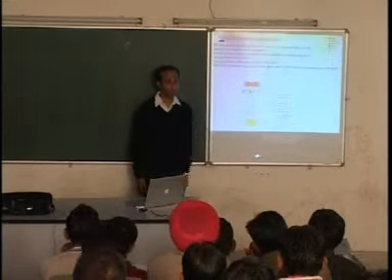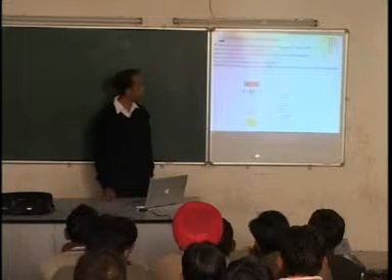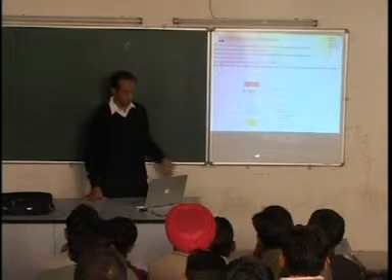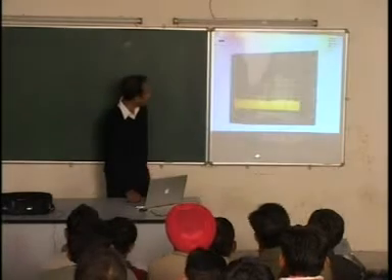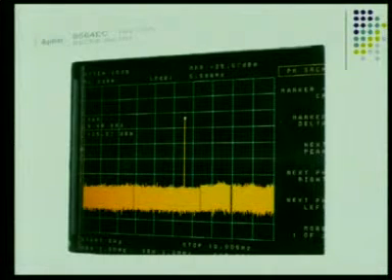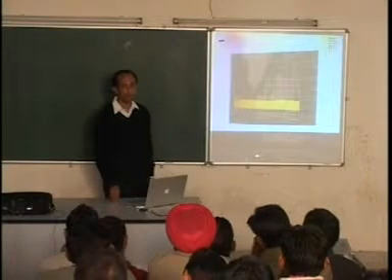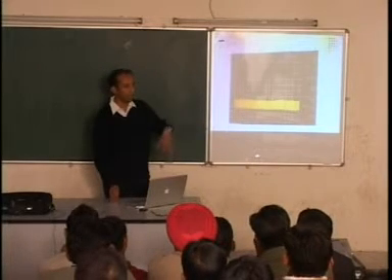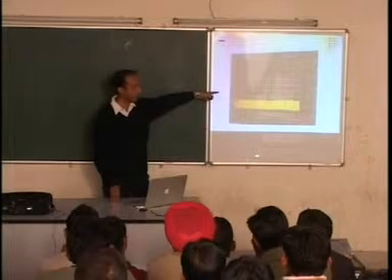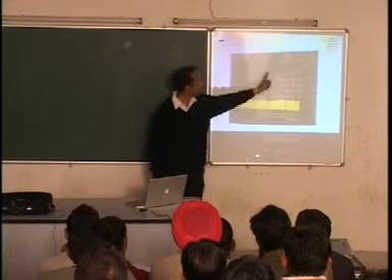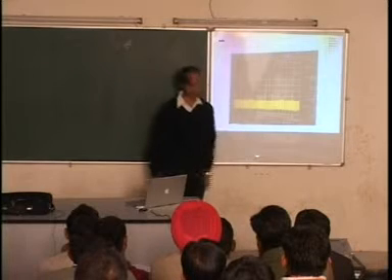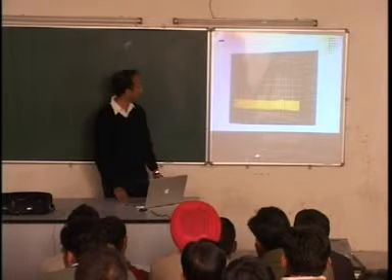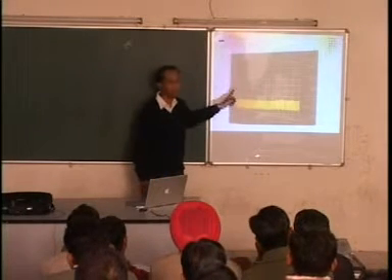This is the transistor. That's the complete circuit. That's what it looks like in a figure. In a photograph, okay, this is the spectrum. How was the spectrum found out? Take a receiving antenna, put it on top of this circuit and see what is the signal. That's the signal. Okay, very pure single frequency at 5.58 gigahertz. So it works. There is no jump, no 1 point something gigahertz.